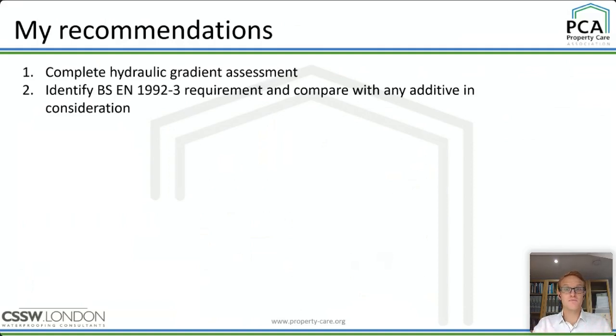And then we need to be using some professional judgment, saying, well, is that feasible? Is that viable? Because if you try and get your crack widths down very, very low, you can end up with so much rebar that there's not enough room for your concrete and you can get voids. So you need to be using your professional judgment in that.